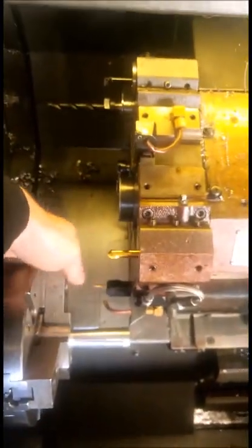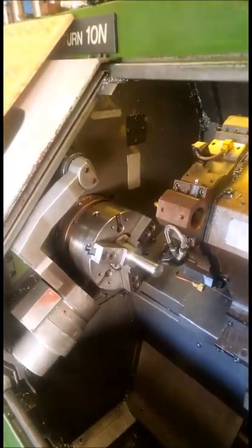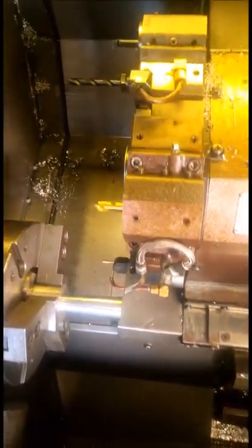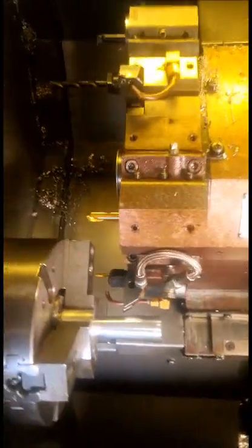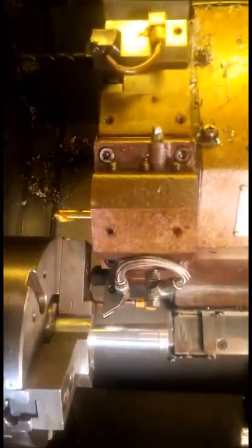Chuck X, sorry. This is the outside limit of your chuck. This is for a chuck barrier, so hopefully you don't run tools into your chuck. Set that at 210 because my jaws aren't hanging outside my chuck. Chuck Z is where your jaws finish. If you want to actually teach that, you can run the tool up however close you're comfortable with. With this, I'm not going to be going anywhere close. And then go C barrier teach.